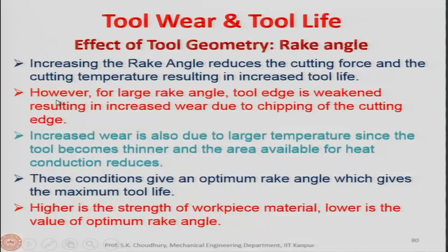So, it is the less effort in the cutting and the less force is applied, and as I said already, the less force applied means the cutting tool life will be increased, and also the surface finish will be better, that is one thing. Now, again for large rake angle, the tool edge is weakened, resulting in the increased wear due to chipping of